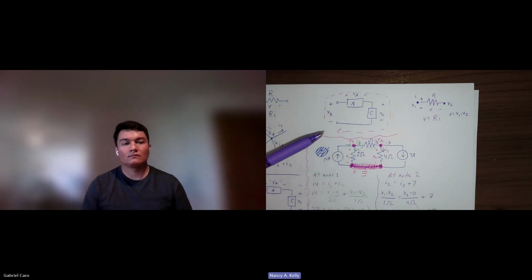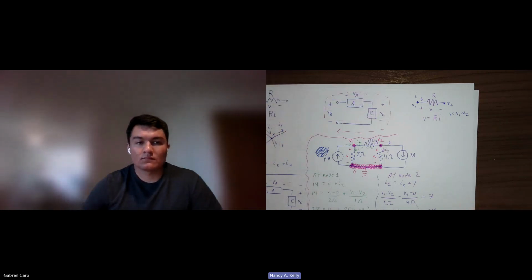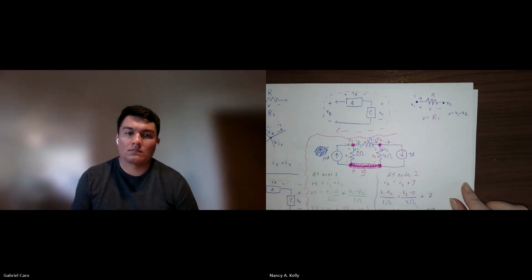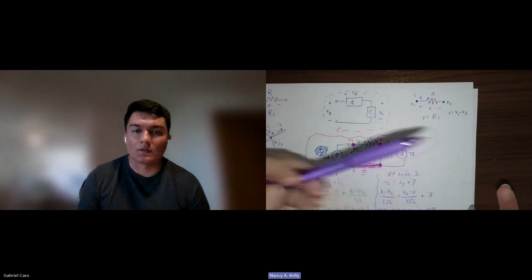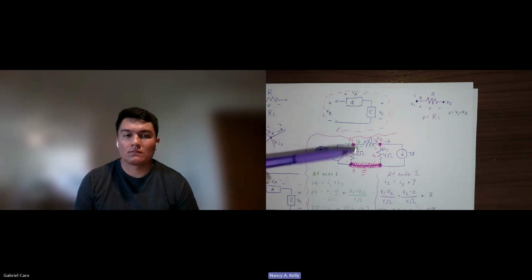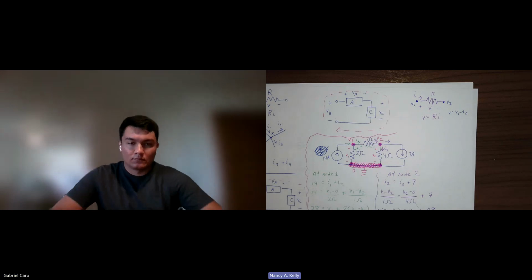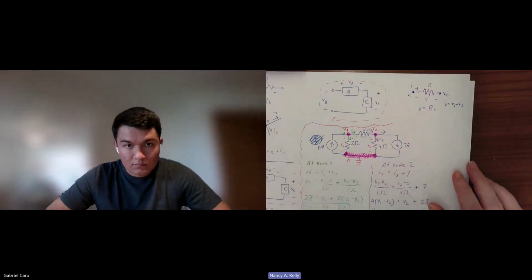So when you're substituting, you have to pay attention to what direction the current is flowing in. When the current is flowing through a resistor, the way I get the voltage across that resistor is the voltage at the node that it enters minus the voltage at the node that it exits. That will come to you easily when you practice. So I suggest that you go over this example yourself. Later I'm going to assign you some practice problems also.